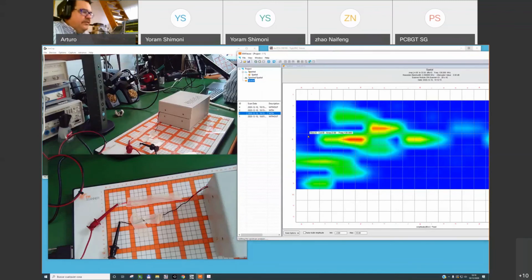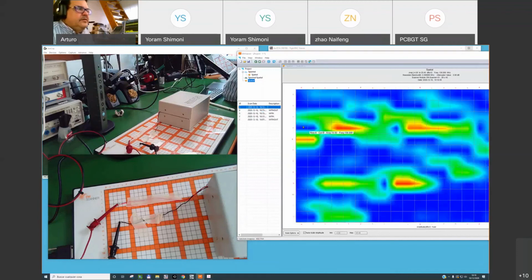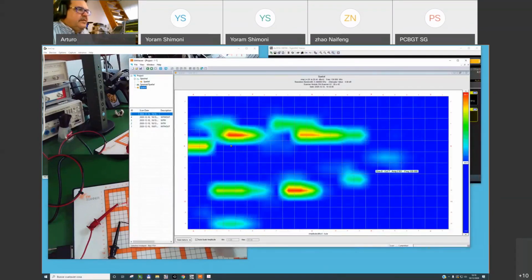Now you will see how effective is the differential mode current, which is big in amplitude, bigger than common mode current, to create a strong magnetic field. Okay, you can see here how is the loop created by the magnetic field. Usually, when you see that the current is taking some blue color between different points in the cable, this is because the cable has some kind of nulls in current. No? One possibility is that the distance between these points in length is lambda over 4 at the frequency of interest. No?